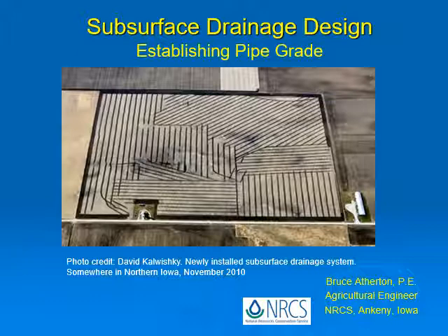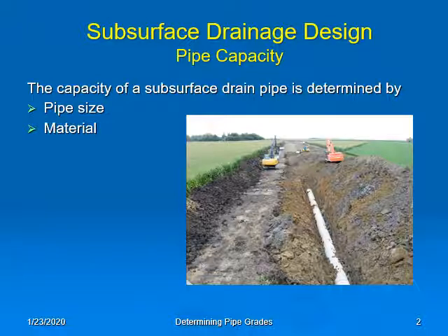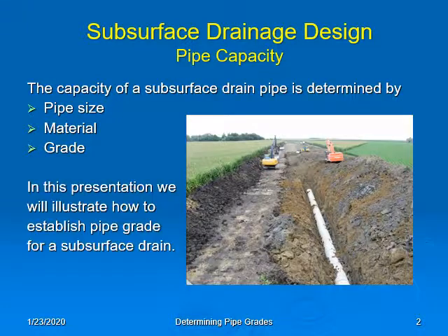Let's get started to learn how to establish the grade for a main and a subsurface drain or underground outlet system. The capacity of a subsurface drain pipe is determined by the pipe size, material, and grade. In this presentation, we will illustrate how to establish pipe grade for a subsurface drain.